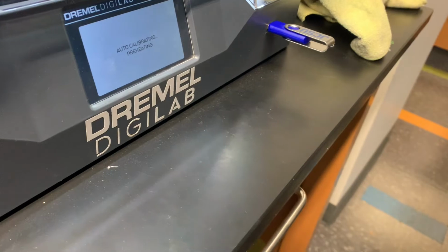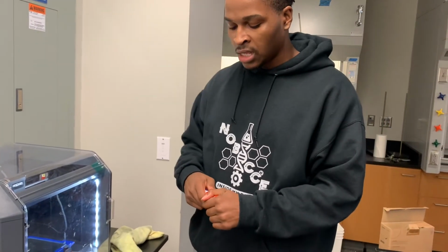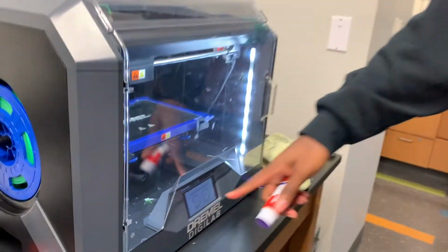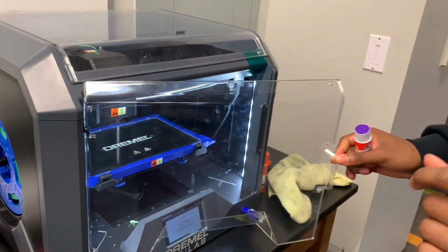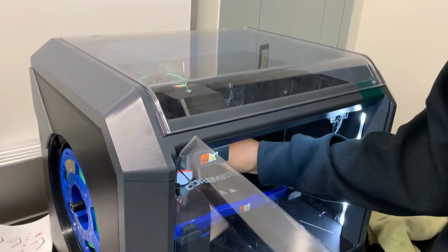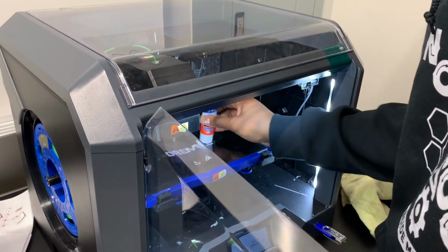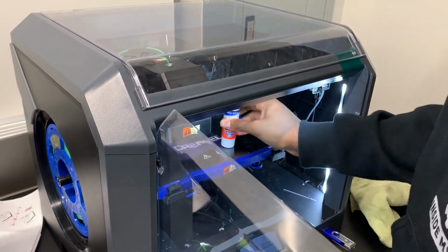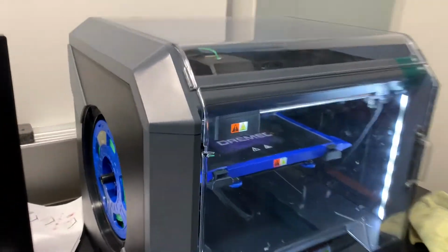Now it's going to do some calibrating, and it's going to heat up your plate. And so when it's heating up your plate, you want to add your glue. So I'll show you that in a second. So once it gets to 200 degrees, you want to start putting your glue onto the spot where you fixed it in the software. So we know ours is going to be somewhere in the middle. So you just put the glue right there in the middle. Now the glue's on, it's going to start printing.